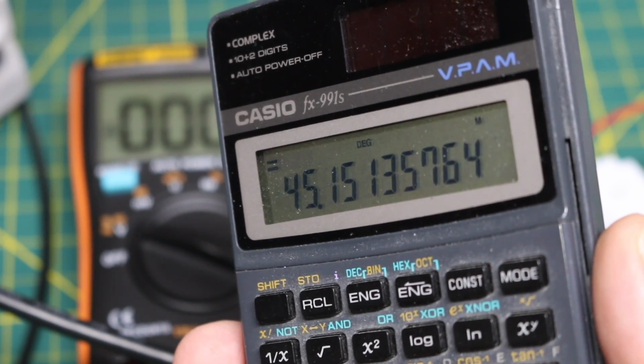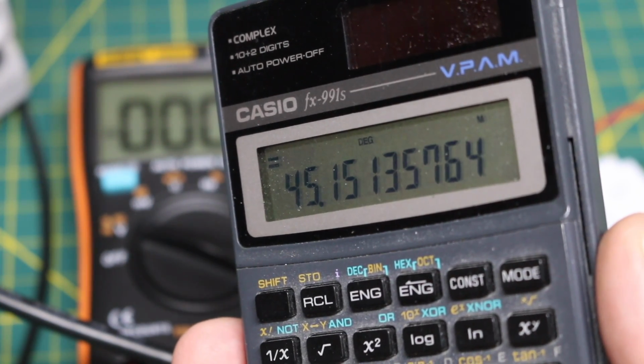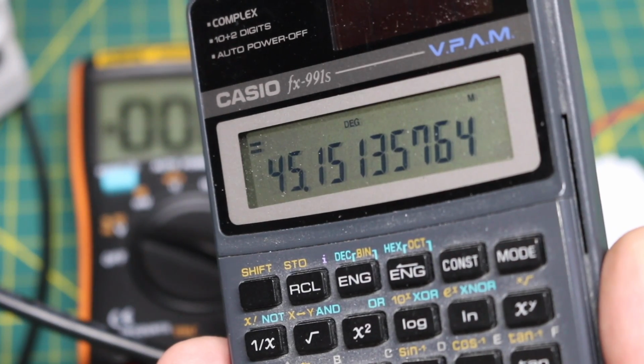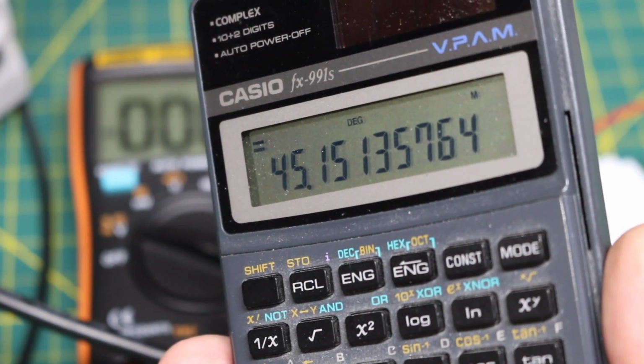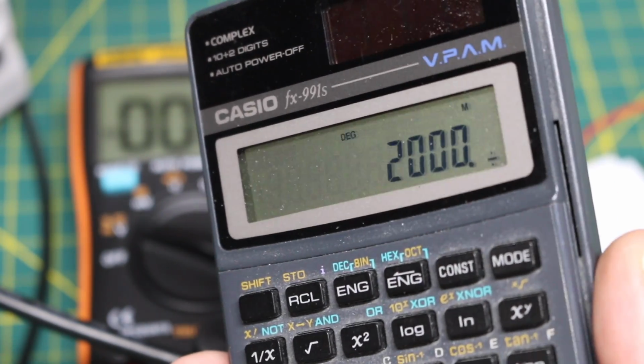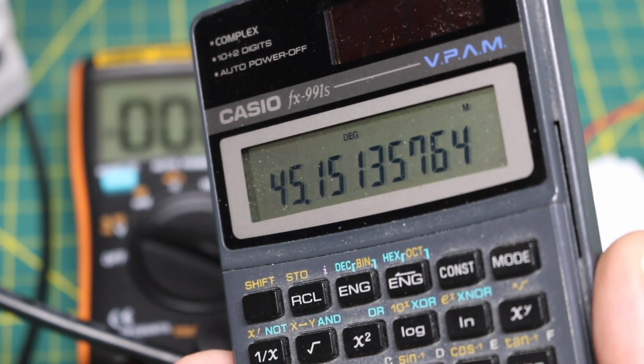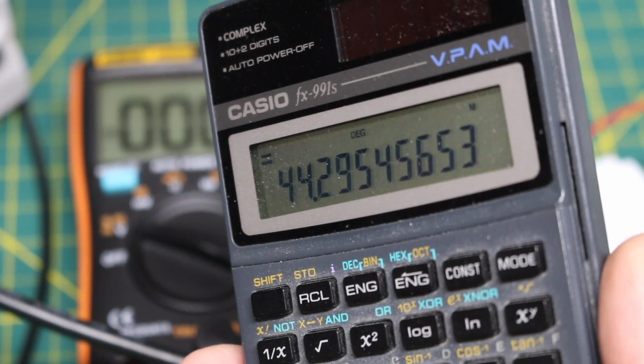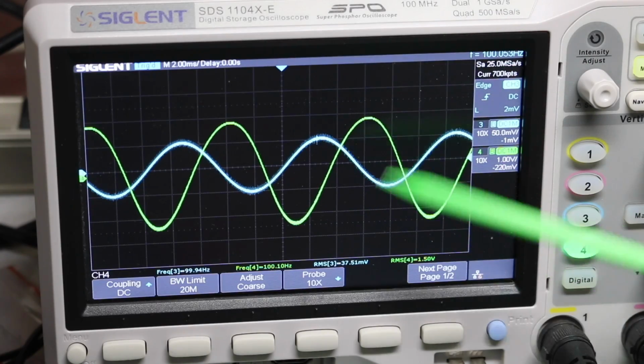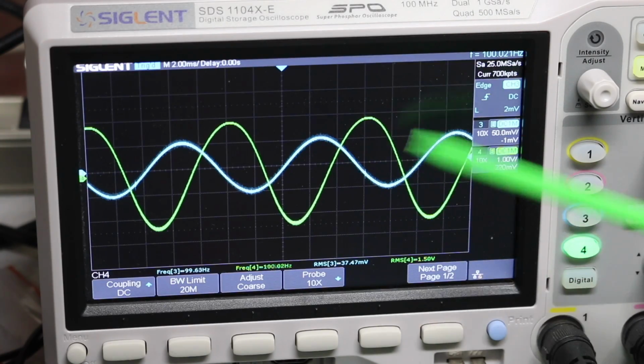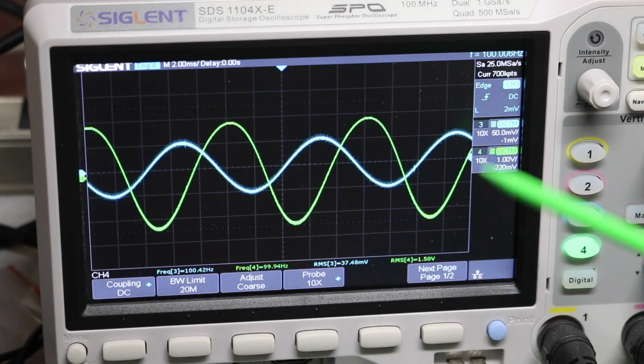So now if we want to calculate the gain using the estimation of RC, collector resistance 2K, divided by emitter resistance, we have an estimated gain of 44. So that's in the ballpark of our measured gain of 40, just for using approximations.